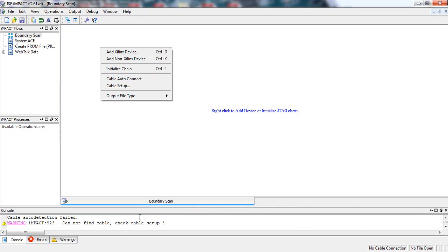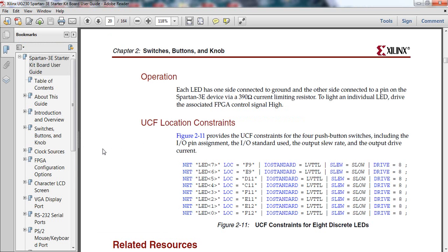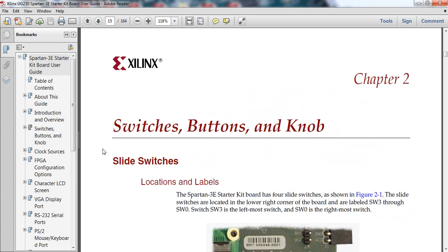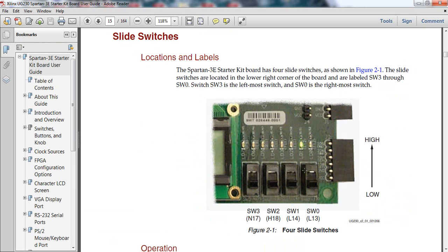Then you should check your hardware by checking the inputs of these 3 switches: 0 0 0, 0 0 1, and if this is high, 0 1 0, 0 1 1, 1 0 0, 1 0 1, 1 1 0, 1 1 1. You can verify all 8 stages. So these are the steps for verifying the design.